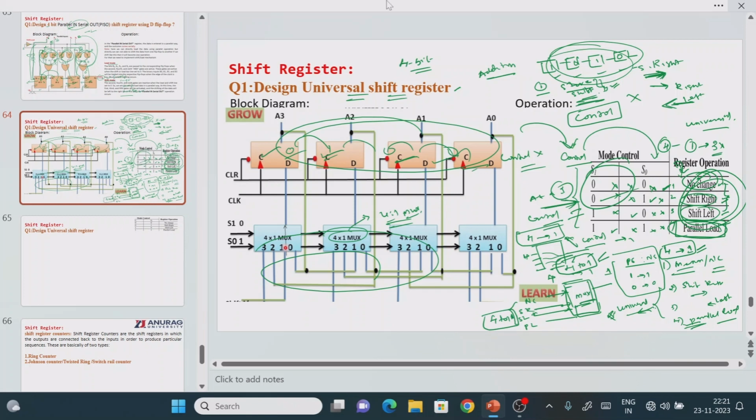Now here you need to understand one thing clearly. The flip-flop can store the value as well as shift the value. But whenever the control comes, out of 4 only one particular thing will be selected at a particular point of time, and this control cannot be performed by your flip-flop. So for that, what is required? We require a different circuit. In my case, out of 4, at a time only 1 should be enabled. It means 4 to 1. So 4 to 1 means what controller? That is nothing but the multiplexer that is required.